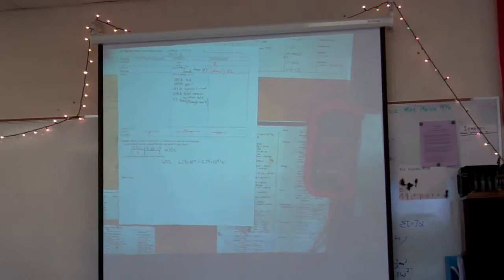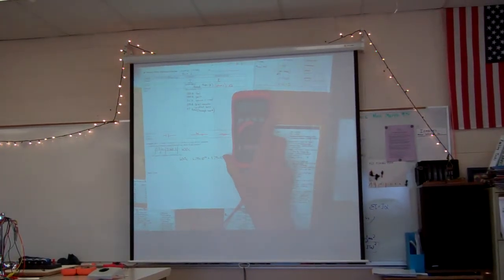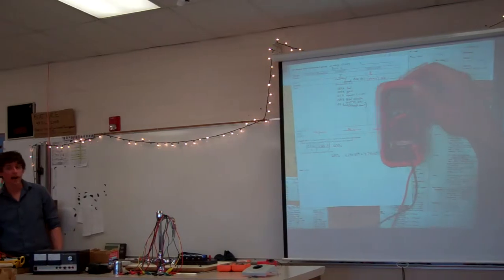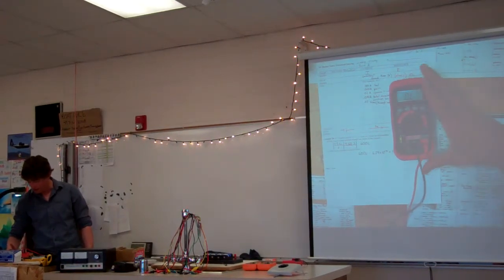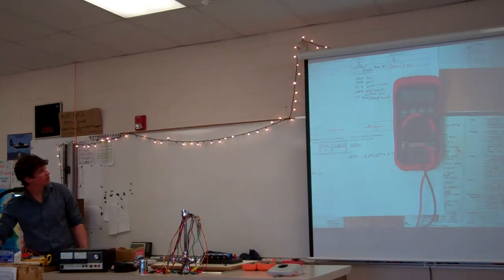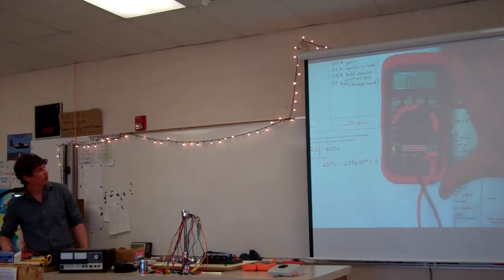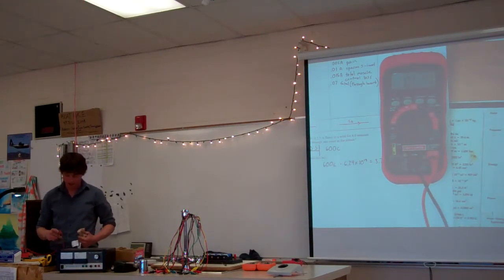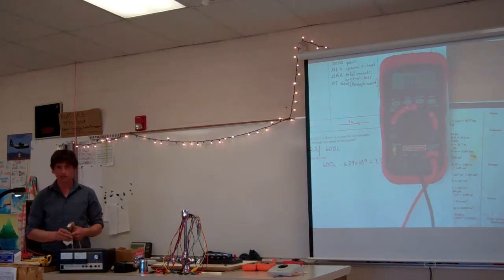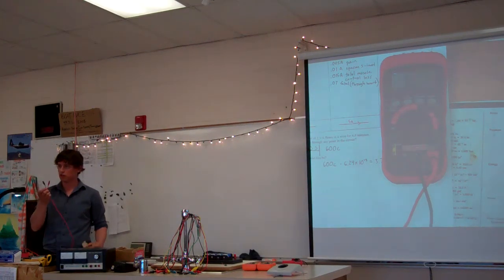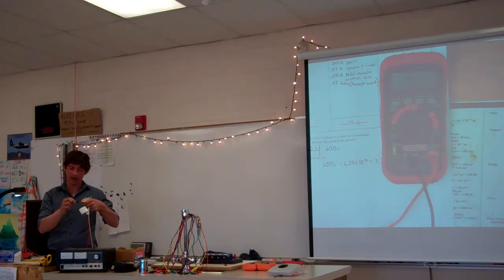And we can measure the resistance of anything, okay, using a multimeter. This is my favorite multimeter. It's a Craftsman, right? Little Craftsman commercial. Okay, now if it says that right there, that means the resistance is too high for it to measure. Okay, so what's that mean about the resistance of air? It's really high. Big. Okay, it's too big for the multimeter to even pick up.